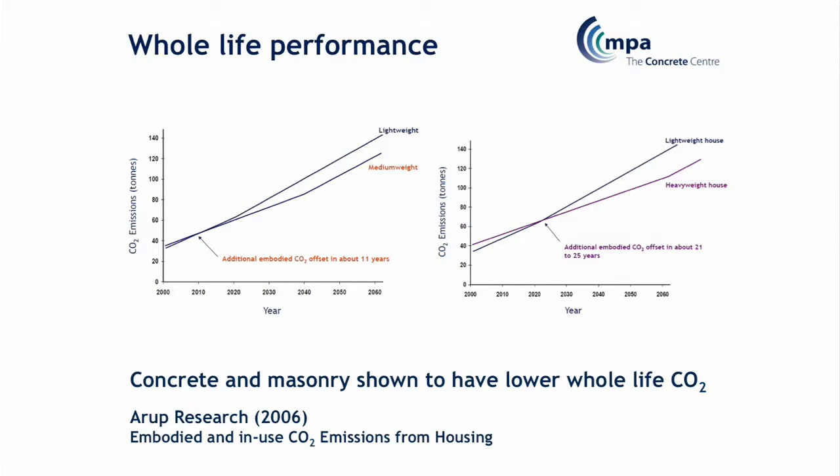And generally there are studies out there. Arup did one a few years ago looking at some housing, which proved that concrete will give you a lower whole life carbon footprint if you're considering the whole life performance, so looking at embodied CO2 and operational CO2. But as we are tackling operational CO2 through legislation, embodied CO2 is becoming increasingly a larger slice of the pie. It's becoming more important, so we do need to think about it. And so that's what I'm going to focus on specifically in this presentation: how to think about that when you're specifying concrete.